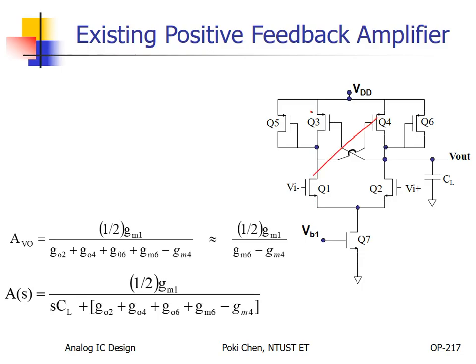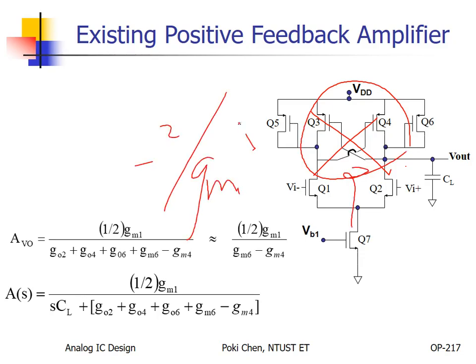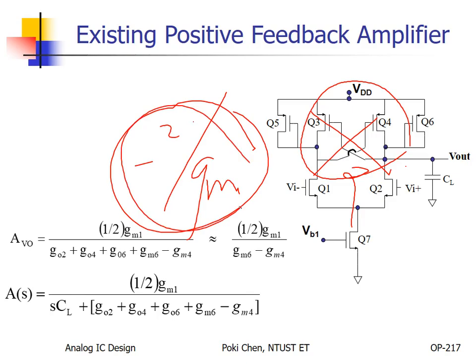First of all, you can see this, such kind of cross connection. In theory, if you apply your small signal analysis here, you can see actually it is some kind of negative impedance. And what we would like to get is to use such kind of negative resistance to cancel the other positive one. For what? To make infinite resistance or zero conductance, zero output conductance. That is what we would like to have.